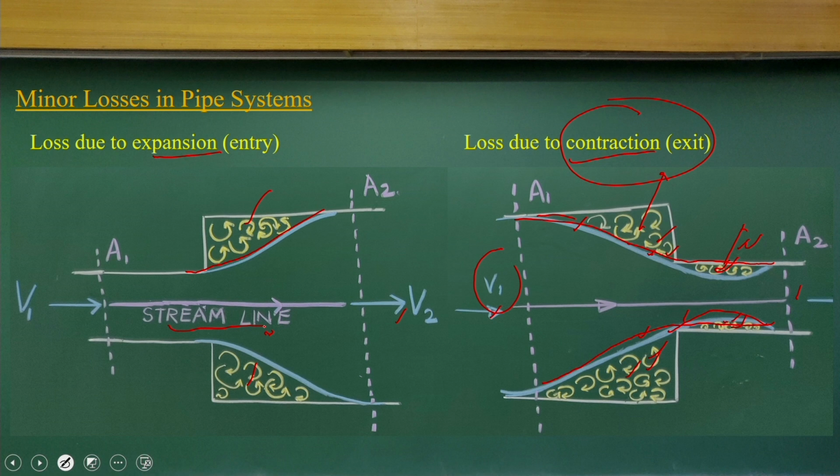Now I am just talking about how to use linear momentum and Bernoulli's equations, which are energy equations. To apply these energy equations, what should I do? I take a streamline. Along the streamline, I should apply the Bernoulli's equation. The most appropriate streamlines are these ones, because these are horizontal streamlines. So we can know the pressure and the velocity, and apply the Bernoulli's equation over these ones,